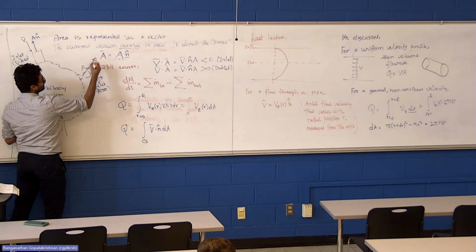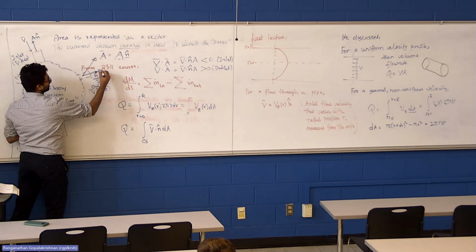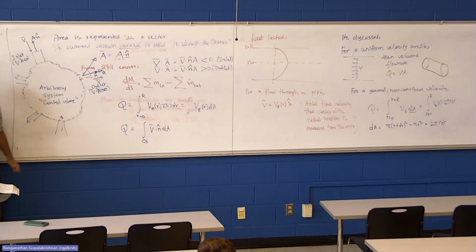The velocity is in some direction, and the normal vector is in some other direction. Now you can think of what part of the velocity will actually contribute for the flow to exit this cross section and what part of this will only slam into the wall up here. Can you tell which component contributes to the flow rate going out of this cross section?